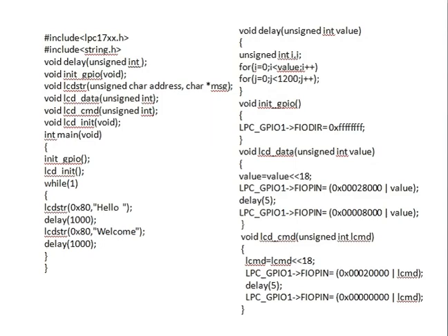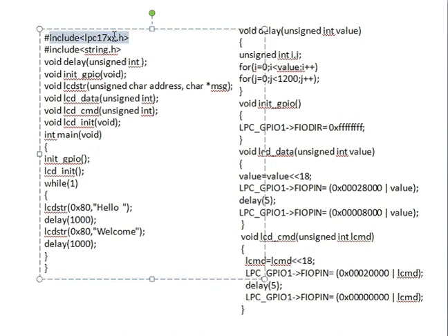Okay, the program we will discuss now. Fine. So in this program, we know this LCD device needs to be provided with strings. Even if it's not used, not at all a problem, but I think it should be used. A string should be used because a set of characters we are passing as an argument to the command lcd_str. So string.h header file indeed is required. And just remember some of the functions which we are using here. I'll discuss that first, then later we will look at how the flow goes.